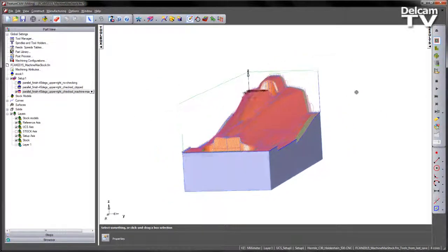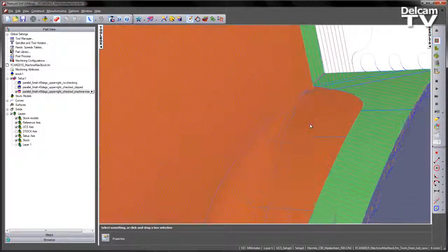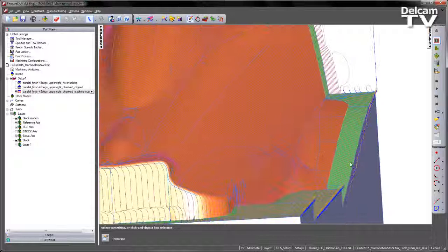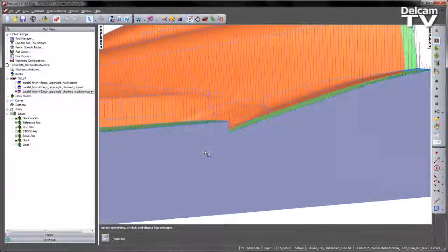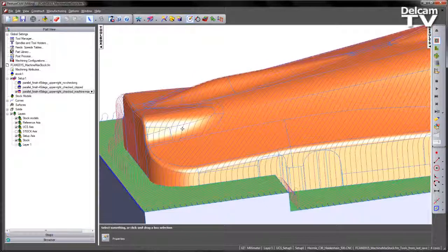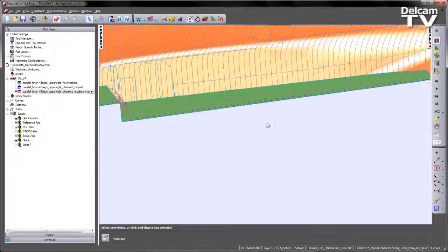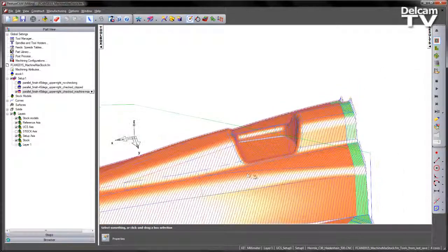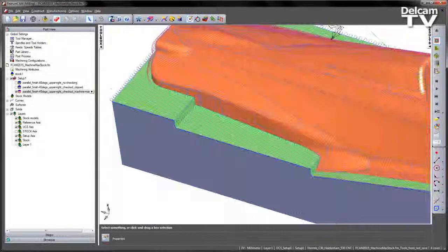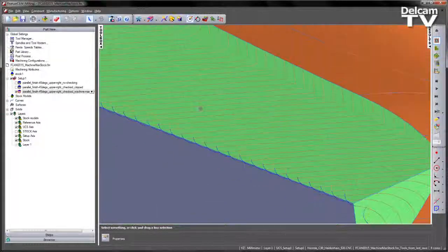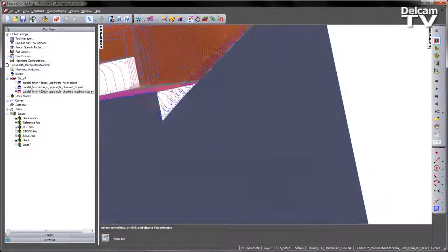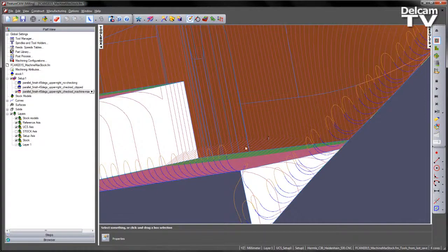However, if you rotate the part round and look at the different toolpath segments, for example, at the back here, you can see the tool gets to the collision situation and then pulls away from the part and then rejoins to prevent the collision. We can see obvious areas, for example, at the front of the component, here, and inside this recess, we can see the toolpath again, like so. I'm rotating just around to this region as the less obvious area, where the tool has pulled away from that edge and given us our collision-free region here as well.